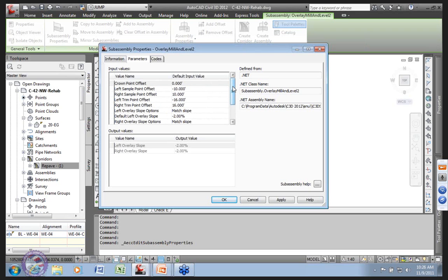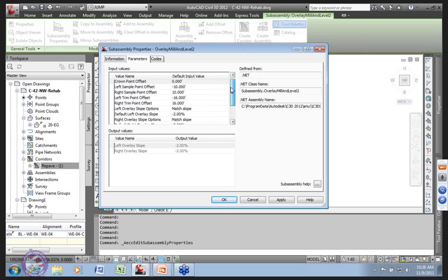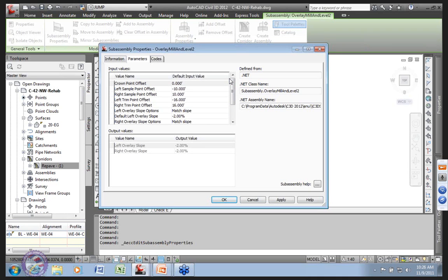And so anything that has horizontal definition to it, almost, as long as it's a Civil 3D feature. But in this case, since we're applying it to our corridor, our horizontal control has to be defined by alignment. So, but not really, because we could go off the crown. Okay, couple of key issues. Targeting.